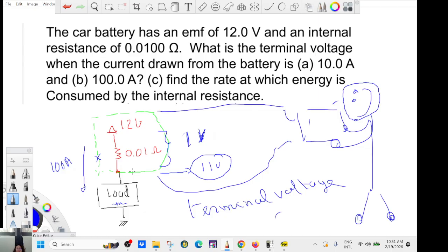And that's what happened to your car battery. If you go to measure and the car is not on, you're gonna read 12 volts. Or you say, okay, it's good. So that's why they have another way to test the battery. I guess they attach a load to it and they see how much is lost. If you have left with 9.6 to 10 volt, you need to change your battery.